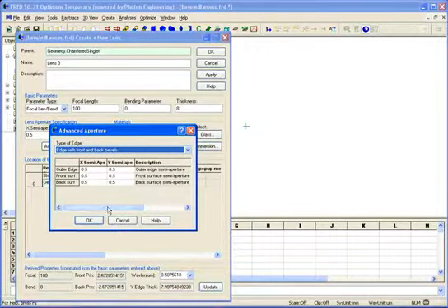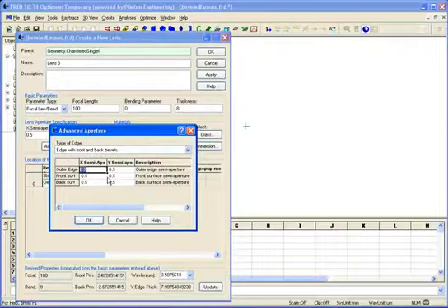Now here I'm going to go ahead and specify the outer edge, that's the full diameter of the lens element. We'll make it 20 millimeters in X and Y. I can also specify the aperture of the front and back optical surfaces. The difference between the outer edge and the optical surface apertures will become a beveled surface. So we'll make this 19 on both sides. So I should have a 1 millimeter edge bevel here.